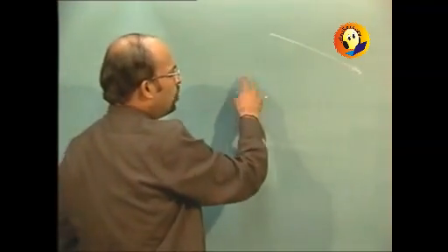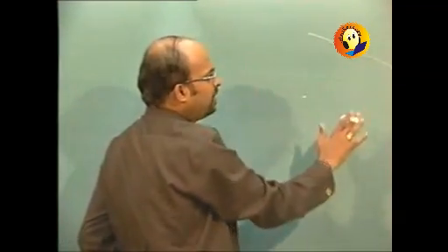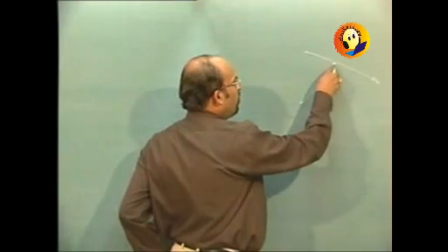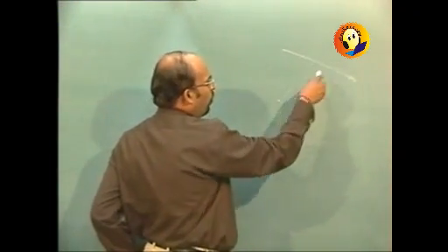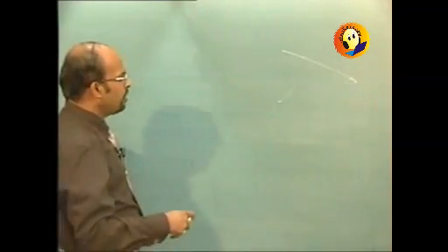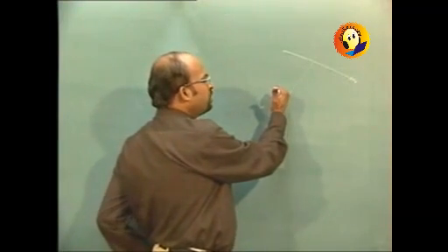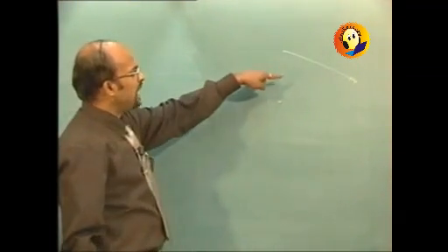So the force and a point together form a plane, which is a 2D problem type of thing, and then we are required to drop a perpendicular from the point onto that particular force and then take the moment. But that moment is always perpendicular to the plane in which the force as well as the point reside. Now this perpendicular sense is obtained through the cross product.